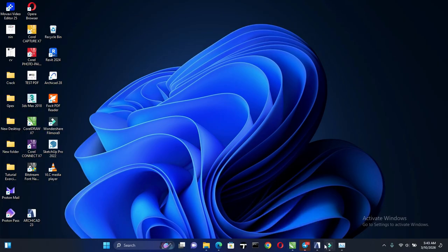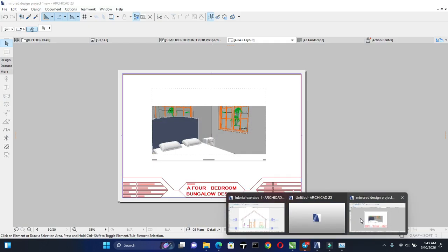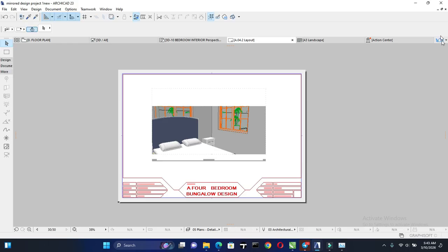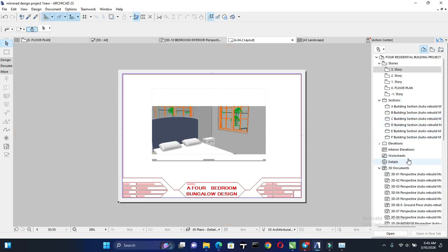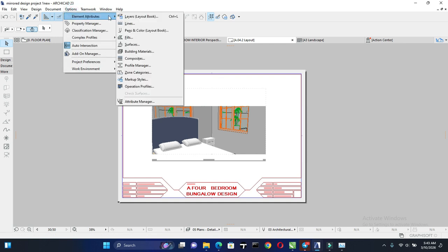When you are done making your changes to the pens, you click OK, and then you update this. When you select any, you see the thickness and the line name. In Building Plans we have 0.5 thickness, but in Architectural we don't; we have 0.35 as the highest thickness. So for Building Plans, we could say OK, and then come here and change it to Building Plans. Okay, so you see Building Plans is already there.